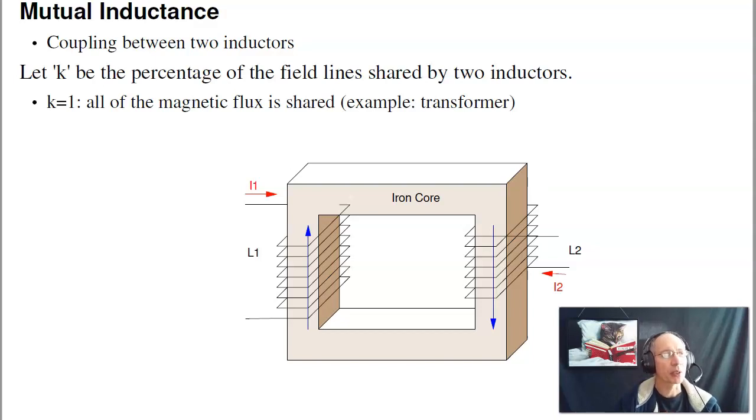That's how they work. For example, suppose I want to have two inductors on the same iron core. The first inductor produces magnetic flux proportional to the amps times number of turns. The units of magnetic flux are amp turns. If this is an iron core, almost all the flux will go through the iron core through the second inductor. So the amp turns on the first winding are equal to the amp turns on the second winding.